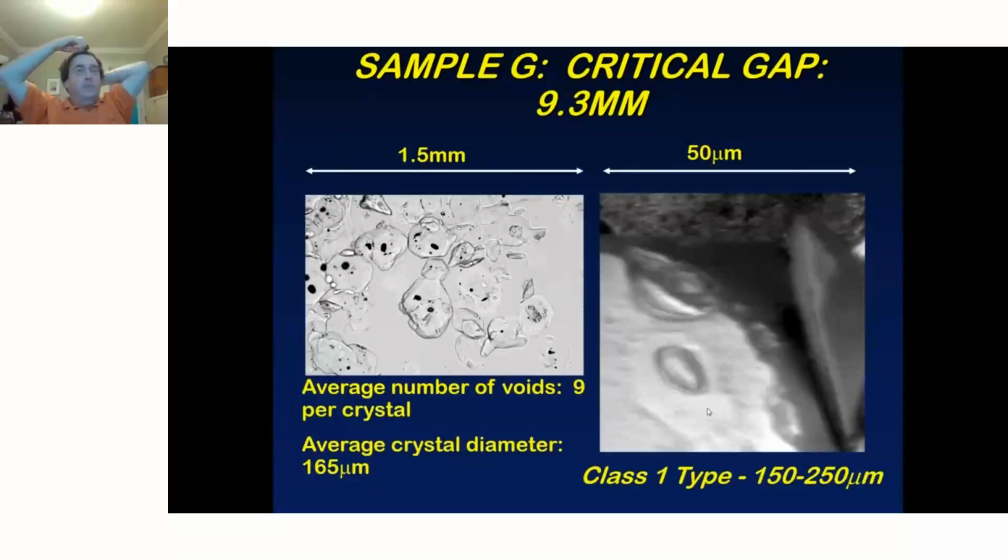Now, if you come from a background that says voids equals hotspots equals reaction, you will say this is wrong. The material with the large number of voids must be the more sensitive material. However, we must remember that hotspots is one of several mechanisms causing reaction to build up.